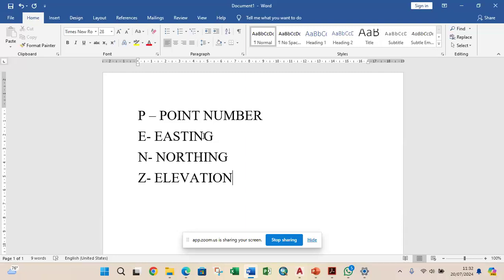So the surveyor now will work on a projection, which we have in Nigeria. I think we have 4 projections. We have zone 31, zone 32, zone 33. If a surveyor is working from Abuja, Benue, Niger, Kaduna, Katsina, all those areas are zone 32. So the surveyor will need to do a proper setting out and programming of his instrument to suit the particular area he's working in.